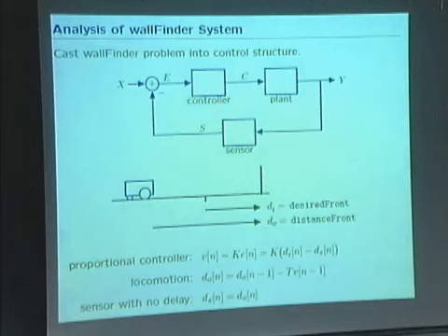The sensor, we're going to assume for now, is just perfect, okay? It immediately tells me the distance to the wall and gives me that perfect feedback. And then we designed a controller which just takes the error, the difference between the desired position and the actual position, multiplies it by a constant k, and comes up with a velocity command that goes to the motors.